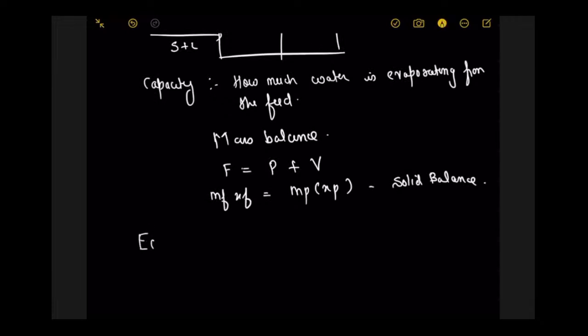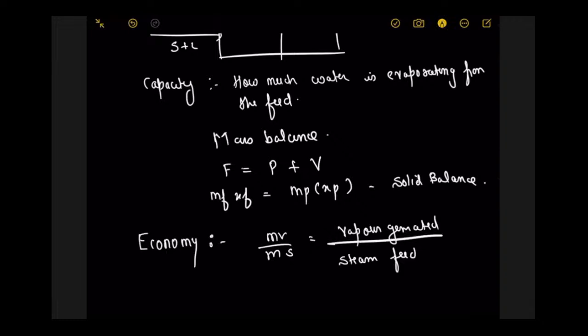Now there is a term, economy. Economy is vapor generated upon steam supplied in the feed section. So a good heat exchanger is one which has a more economy.